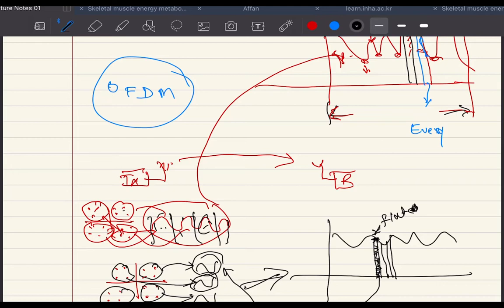The 4G systems are trying to eliminate this kind of error in the channel, the error happening in the frequency selective channel. The data is sent into multiple bins or multiple subcarriers, and those multiple subcarriers will have the flat response even for the frequency selective channel, which would not be possible in the single carrier system.